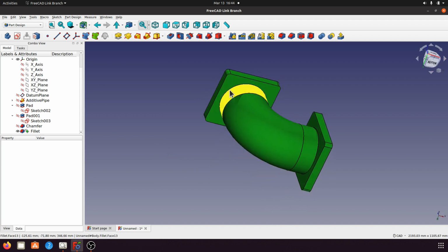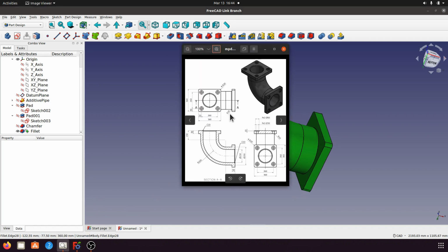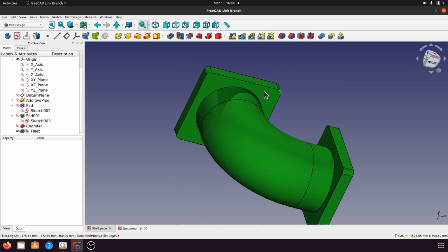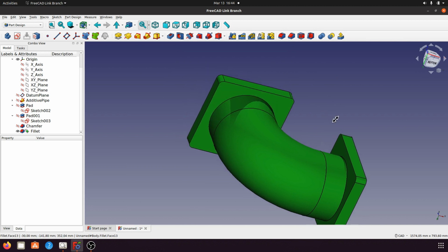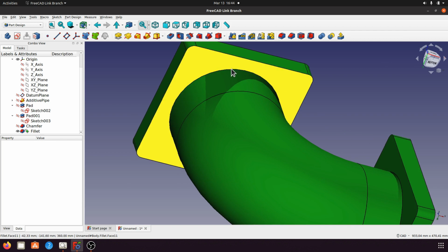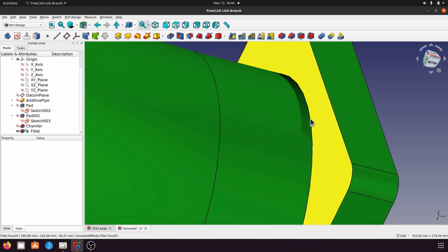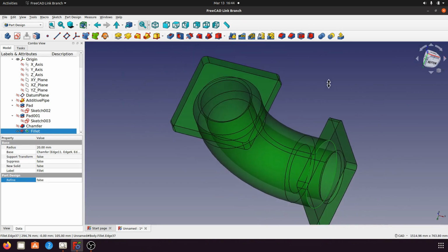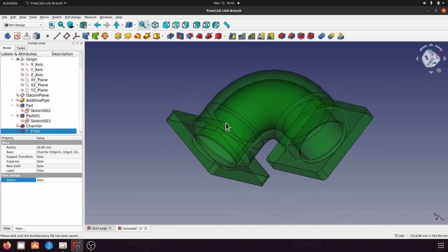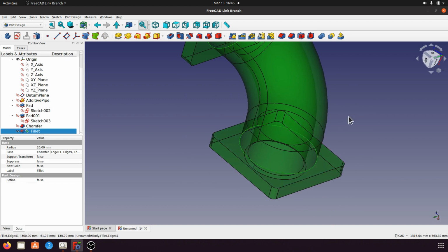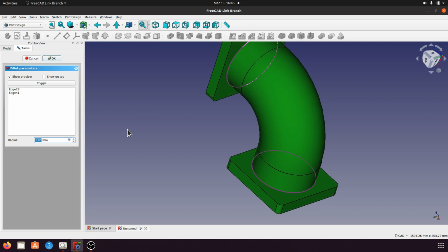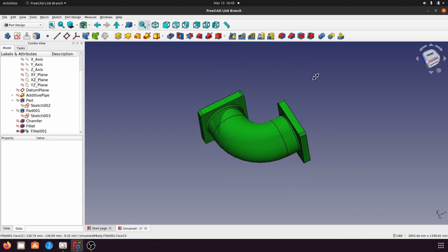and the last one for the fillet, radius 10 millimeter. So click this circle, okay. Sorry, using control. Okay, now let's choose fillet for 10 millimeter. Click OK. So fillet and chamfer is finished.